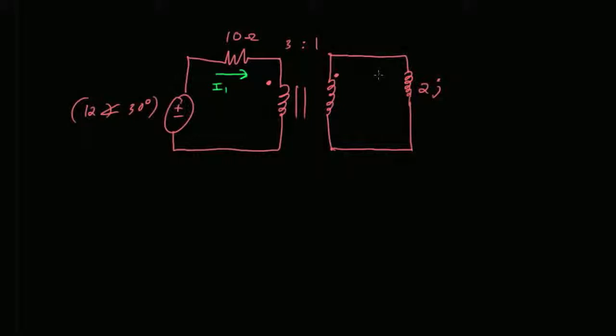So just to summarize what we learned so far for three-phase circuits, there are basically two ways of configuring them. You can either have the Y configuration or the delta configuration. The key difference is that when you use the Y configuration, you have the presence of the neutral signal, so your voltages are measured relative to neutral. Whereas when you use the delta configuration, your voltages are not measured relative to neutral. They're measured relative to each other.